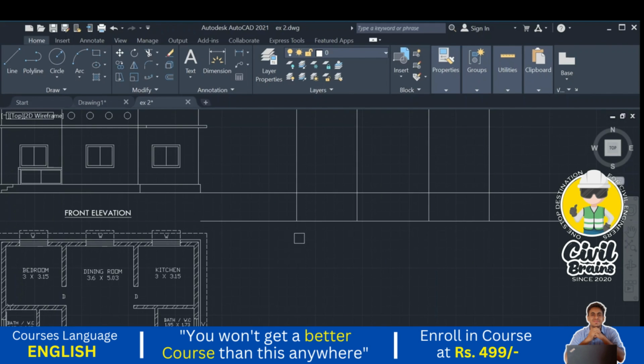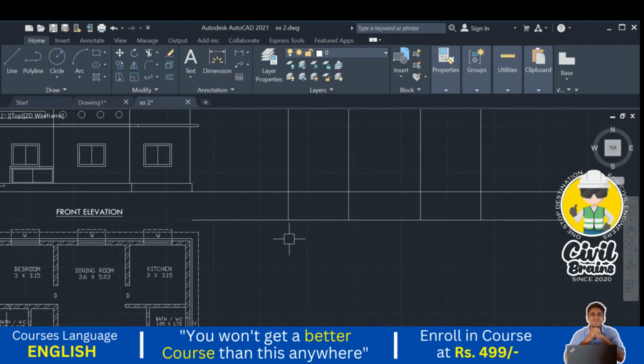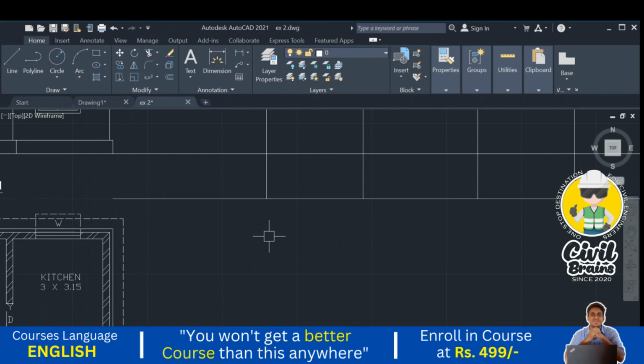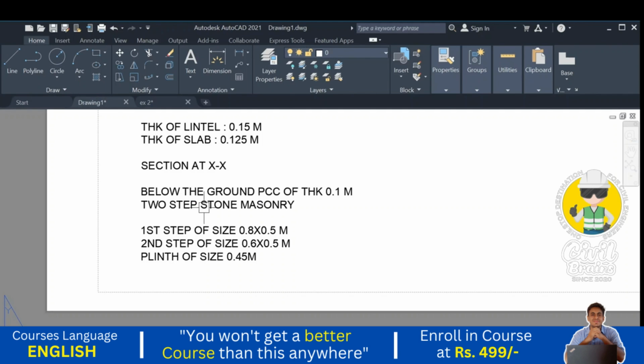Okay, correct, fine. Next, what is the width of the excavation? It is mentioned here. The first step masonry, that is the larger one, is 0.8 meter. This is 0.6, this is 0.45. So this first step is the larger one, 0.8 meters. That is the size of the stone. 0.8 is the width of the stone masonry.